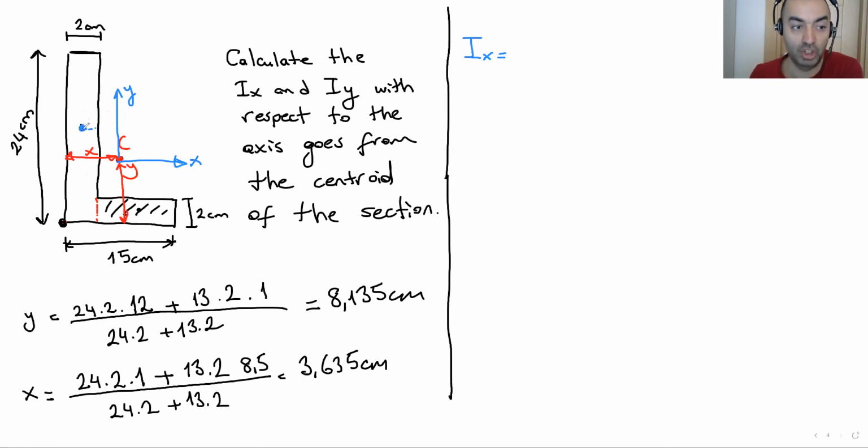Then we will shift this moment of inertia to the global x-axis. We are going to calculate first for the local x-axis. Then we are going to shift it to the global x-axis, where we are going to use the parallel axis theory. Now let's read. For this rectangle, by the way, this is the local x-axis, this is the local y-axis. Okay, these are the small axes. What is the moment of inertia for this one?